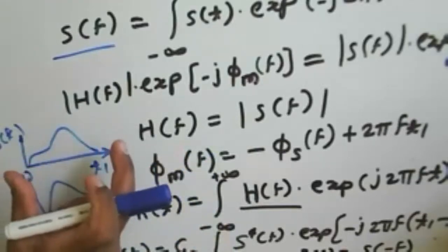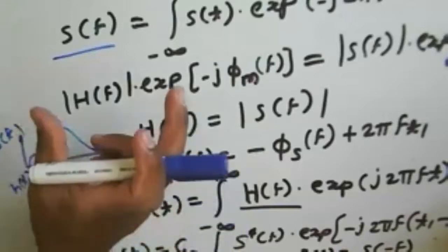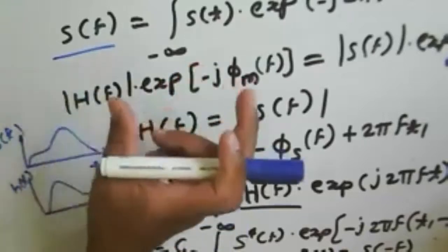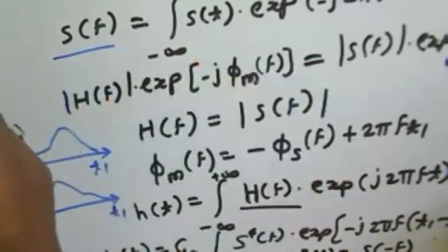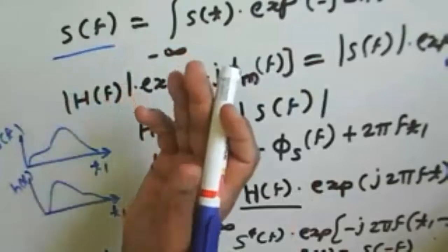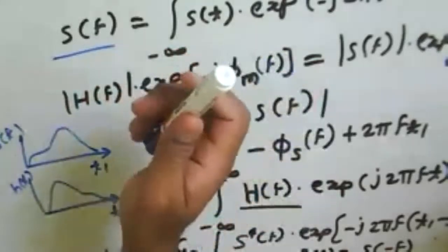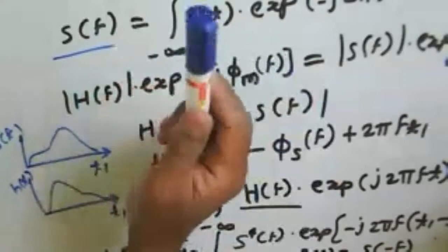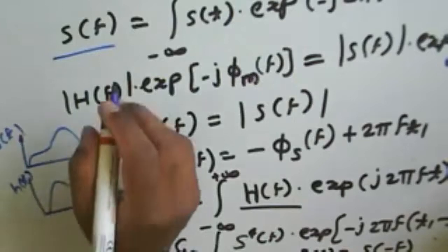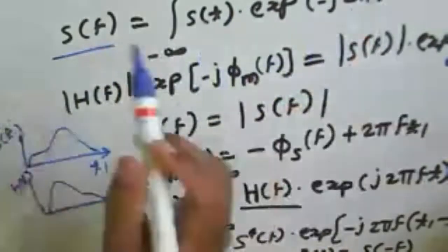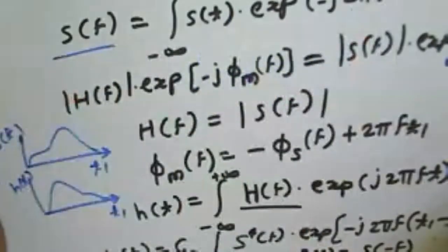Sometimes the impulse response function needs to be written in terms of S of minus t, and generally we say that t is less than 0, but we need to consider that t is less than t1, and then we can find out the conditions for h of f for a given signal to noise ratio. So what will be the filter characteristics of a matched filter?